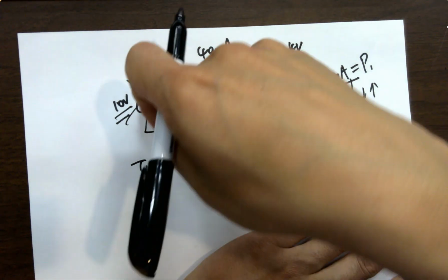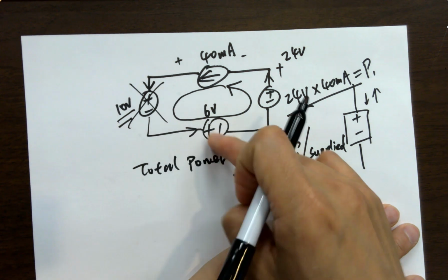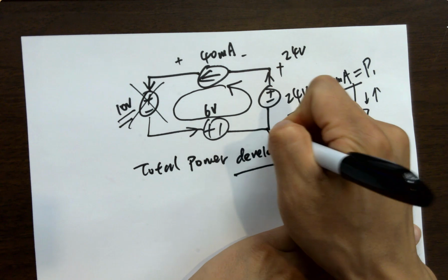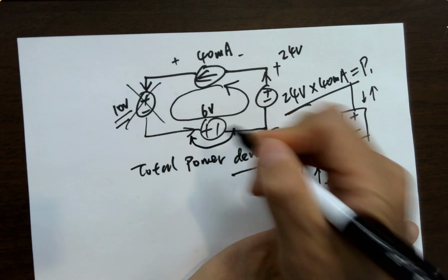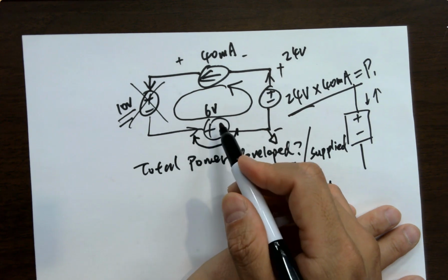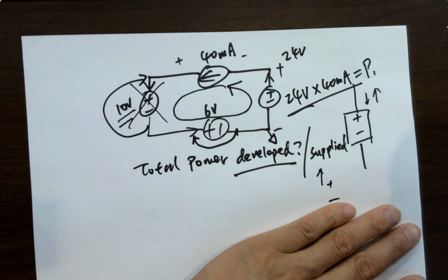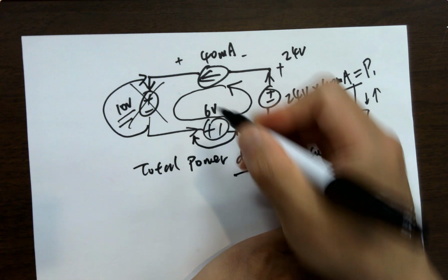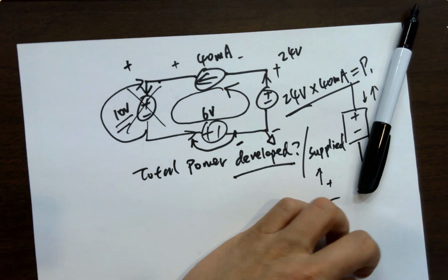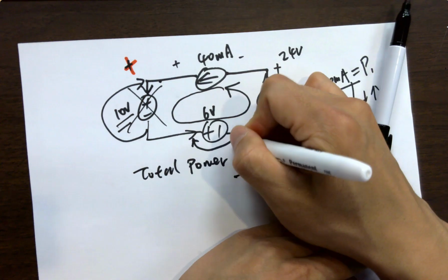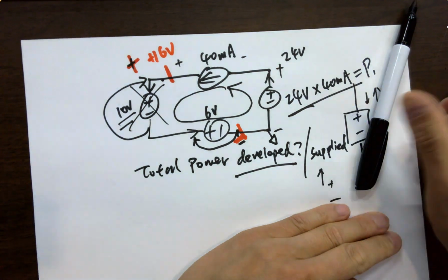And when you put the two batteries in series, they are basically adding up the voltage. Why? Because, for example, you take this as a reference. Voltage from here to here is boosted by the battery by 6 volts, right? And then from here to here it's boosted again by 10 volts. So basically from here to here you are getting 16 volts. These two terminals, you are getting a 16 volts difference between these two nodes.